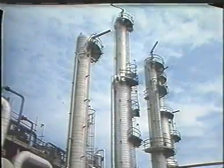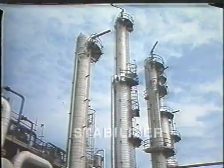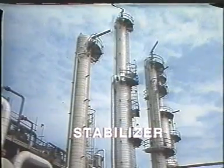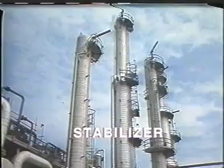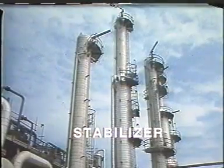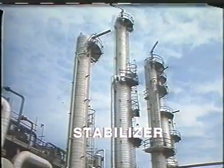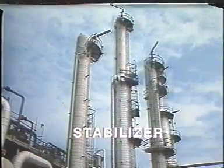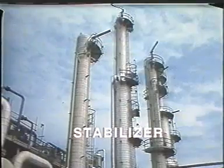The vapor pressure of the reformate is controlled in the stabilizer. Prior to stabilization, the reformate vapor pressure may be several hundred psi or higher. Stabilization removes light hydrocarbons from the reformate, which reduces the vapor pressure to around 5 psi.